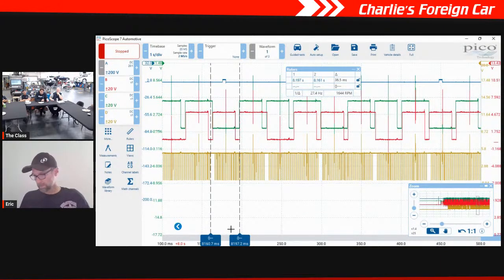I have the impression that when an exhaust cam is sitting in its default position, it's sitting advanced, and the intake is sitting retard, and then when it starts, they go up. So now they're centered. Well, they should be locked, right? When exhaust and intake both have VVTs on them, they should be locked, right? The sprocket should be locked to the cam. Yeah. All right, so that's going to be their base timing configuration, right?